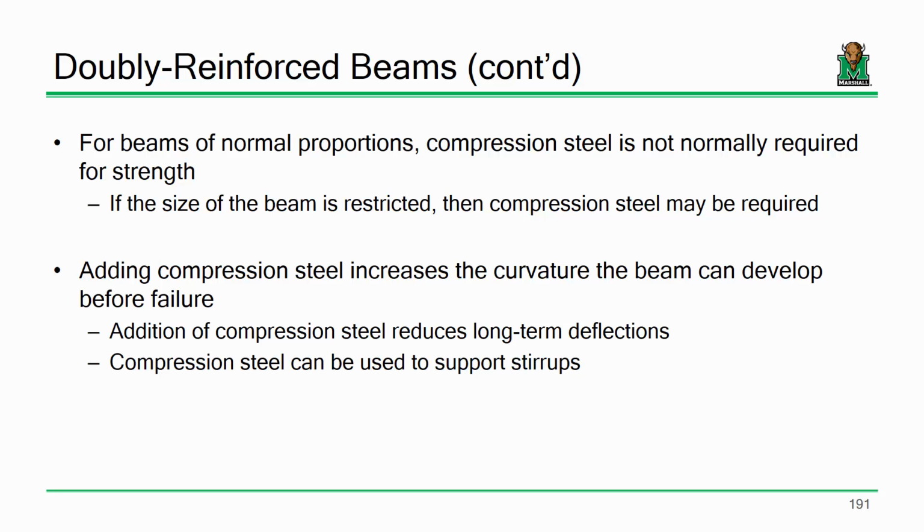So I went off on a little bit of a tangent there, but these are material-related aspects, and it's also something you have to consider when you do pre-stressed design. If you've ever been to a pre-stressing plant, you know that what they do in pre-stressing is they apply a significant amount of pre-stress to a given steel element, let it go, and then that locks in a compressive force inside the beam.